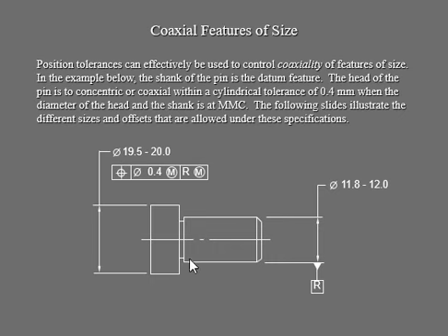Okay, so let's take a look at our very first position tolerance that we are dealing with. And here is your control frame right there. Your unit system is metric because you see the 0 in front of the decimal. I'm saying this again and again; you should be able to get it by now. Your diameter for the head is 19.5, and it has a zone which goes all the way to 20.5. So the width is going to be 0.5.